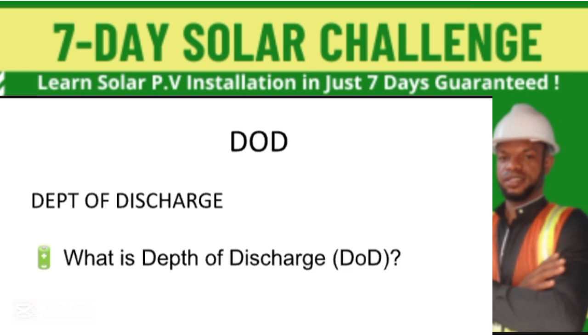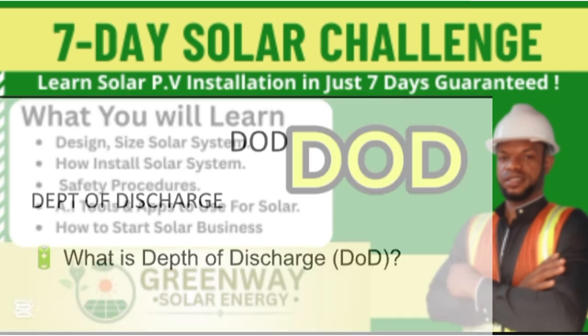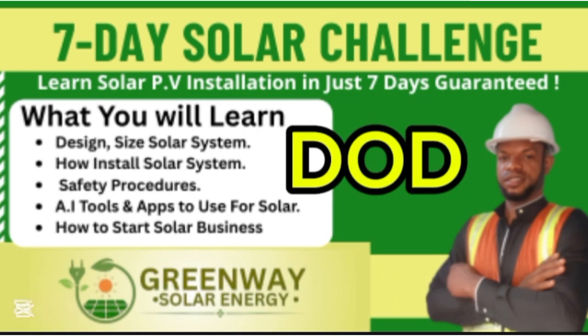Unlike lead acid batteries, if you attempt to discharge them below their safe zone, which is 50%, you are going to put the battery into trouble. You are going to affect the lifespan of the battery and their capacity to deliver along the line.